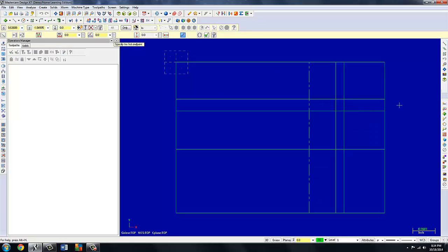I'm going to go to line endpoint and begin working on those angles. The 35-degree angle actually originates from this point, and it is at 90 plus 35 for 125, enter. And lo and behold, it follows right along that intersection that we've got. So we had redundant information there, but it's okay because it serves as a verification that we are on the right track. And it also saves me a trim because I'm just going to drop it in at that intersection.